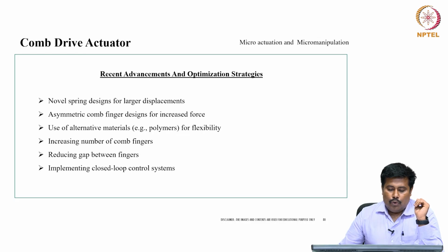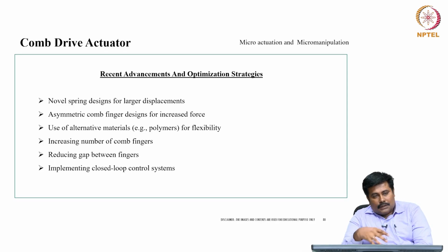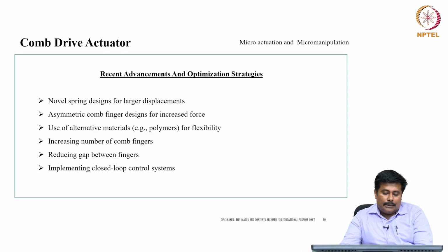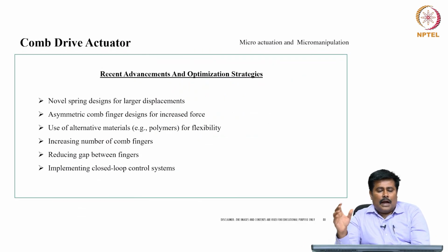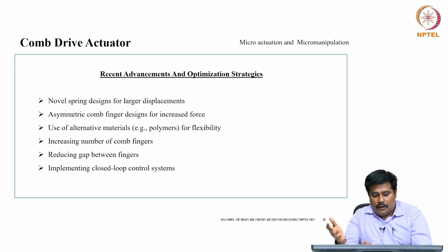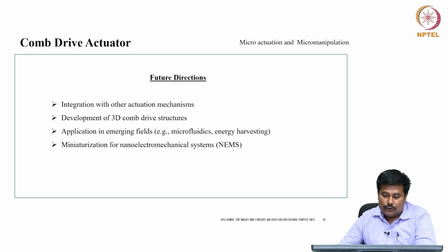With respect to recent advancements and optimization strategies, a novel spring design can be employed for generating a larger displacement, as mentioned in this particular single-sided electroactive system. Asymmetric comb finger design for increased force. It uses an alternative material, for example polymer, for flexibility, increasing the number of comb fingers, the reduction in the gap between the fingers, and it has quite a good amount of implementation with respect to closed loop systems.